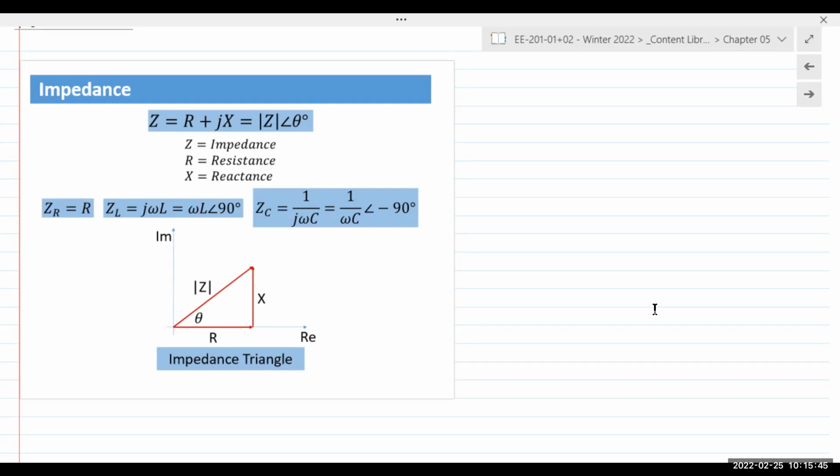As long as the current remains constant or steady, meaning DC, the inductor behaves like a short circuit. The moment you start to change that current, that stored energy is going to oppose any change in that current. Okay, so for DC, the inductor behaves like a short circuit. When you start to change it, the opposition appears. That opposition is described as reactance.